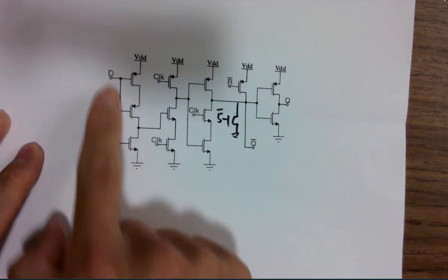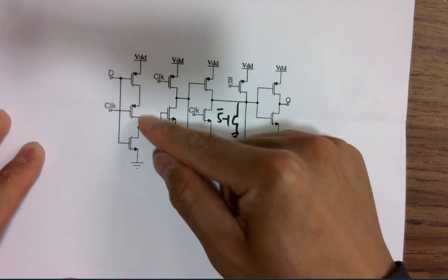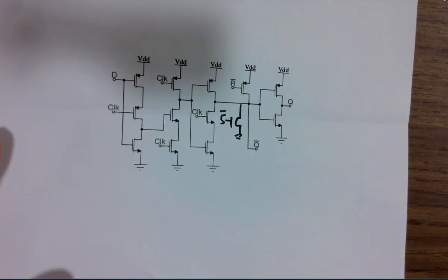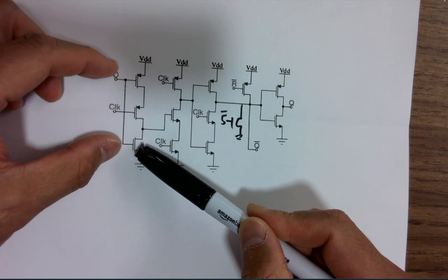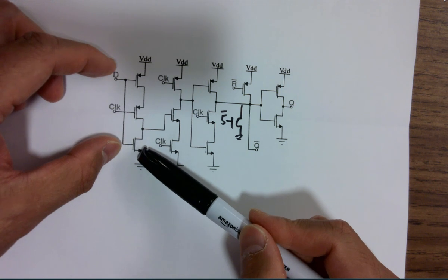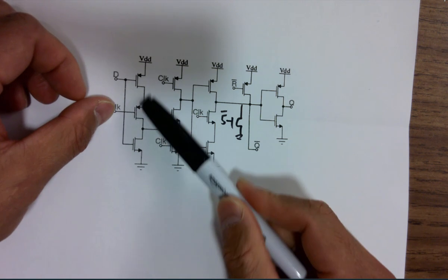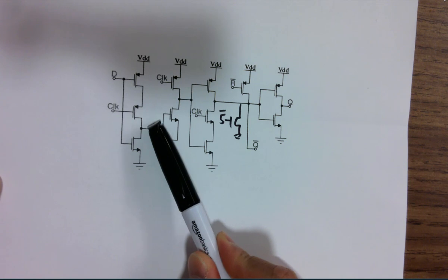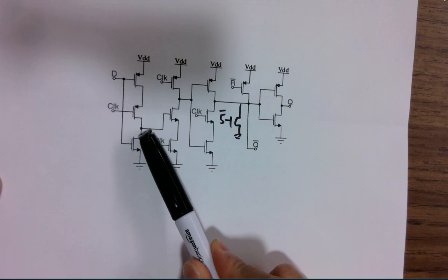So if you look at D here and look at this structure, even though there's a little tiny channel in the middle, what this looks like is PMOS on top and NMOS at the bottom, the gates are shorted. What is this? It's an inverter, right? It's a clocked inverter. You've got one clock in the middle controlling the channel, so sometimes you can turn it on and off. And you can see this output is shorted to the lower side instead of the higher side, which will determine some properties of the operation. But now let's just look at it.